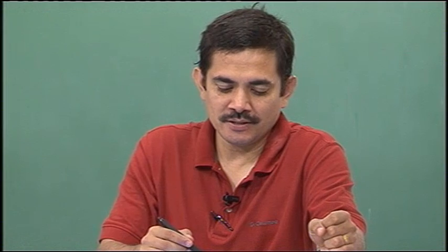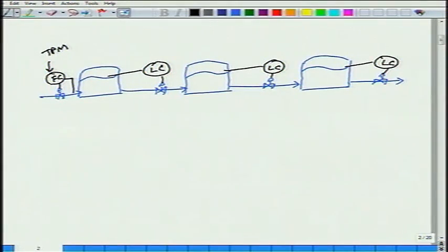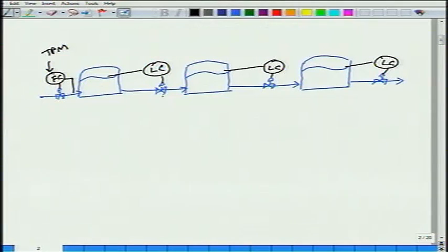He is going to keep increasing this set point. Can he keep increasing this set point forever? Yes, no. Okay, why not? Level controller will make sure it doesn't flood. I increase the flow rate, level controller will ensure the outflow also increases.